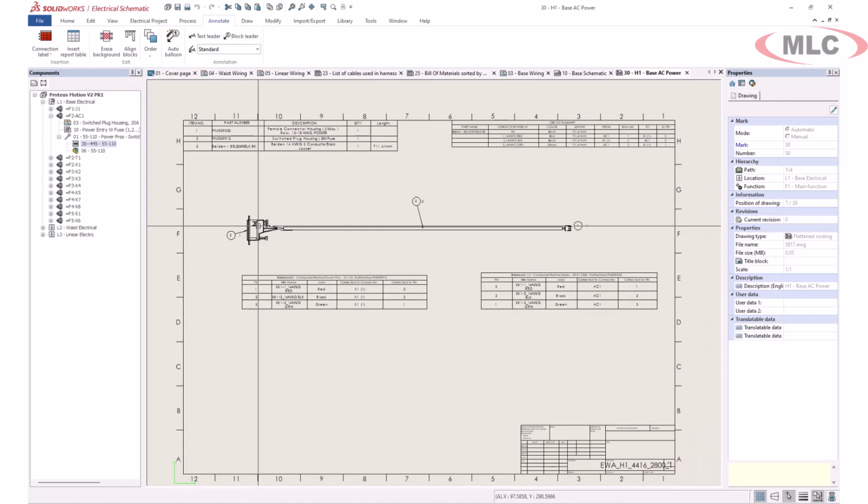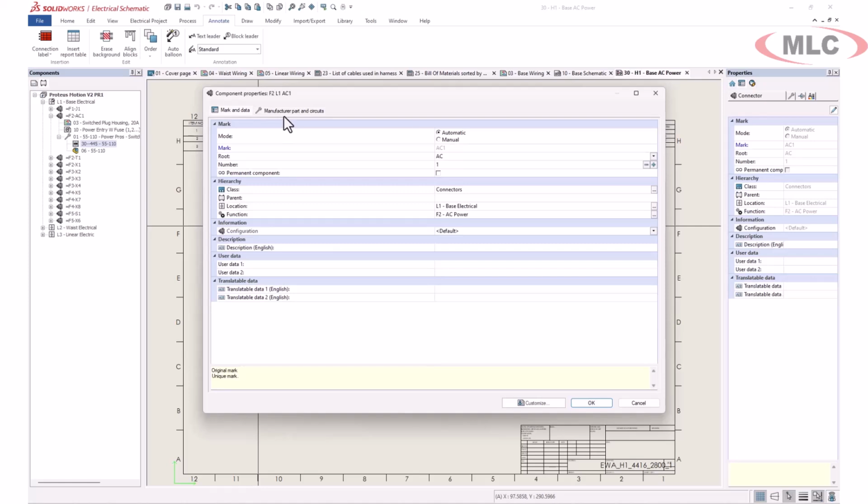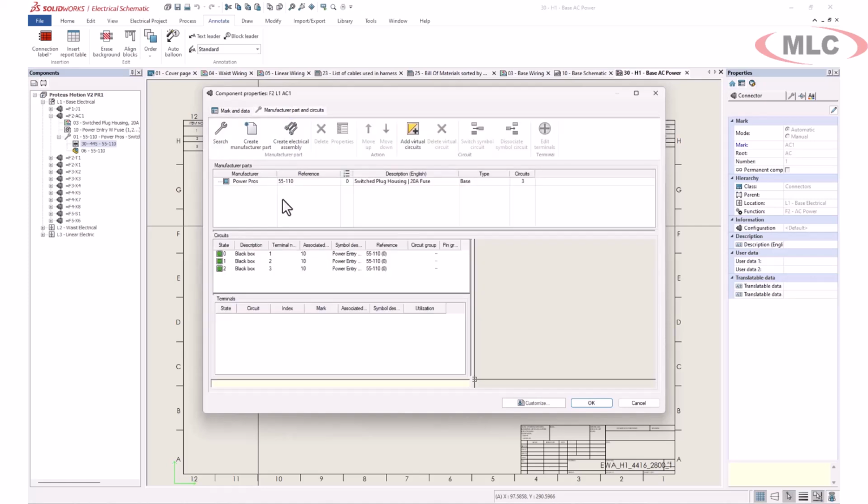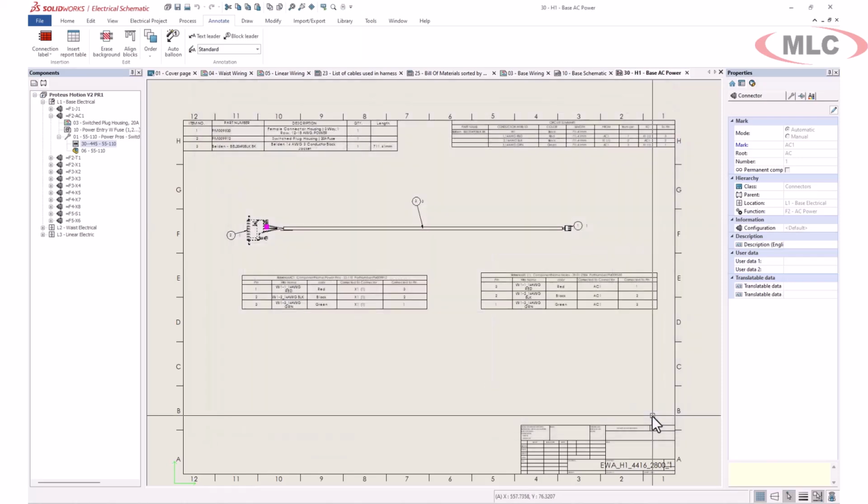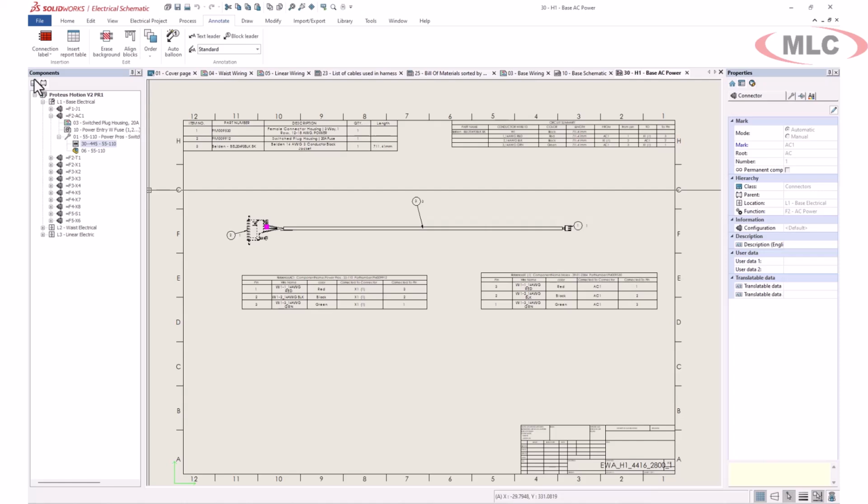That's right, the project drawing from SOLIDWORKS 3D is now fully intelligent. Under the hood, electrical project drawings from the 3D side are now authored with blocks. These blocks link footprint line art with the corresponding component. This means manufacturer part properties, go to linking, and more. Of course, this is naturally extending the electromechanical integration and associativity of representations. This even flows through to the PDF export.